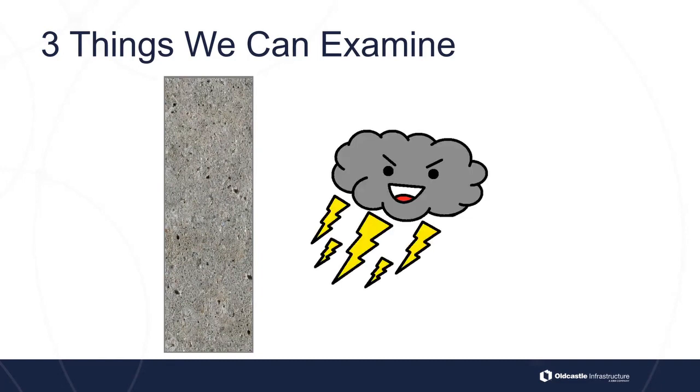All right. The second thing we can look at examining and changing is the environment. Okay. Can we look at venting or encouraging positive movement of air through the system so that it never really has a chance for this H2S gas to build up on the side and form these Thiobacillus, these SOBs, having a chance to form the biofilm? Can we also design the pipe to have lower turbulence so we don't have as many issues with that?